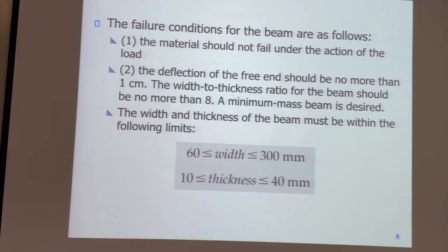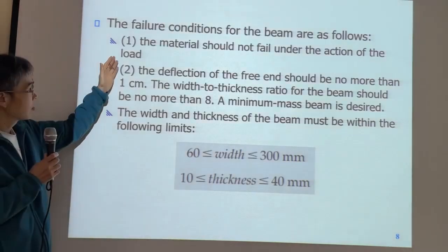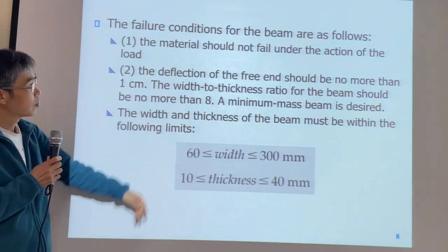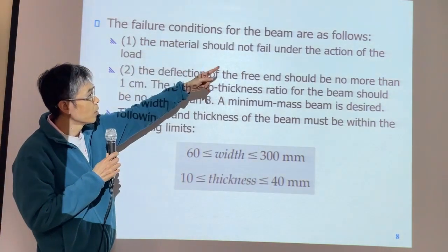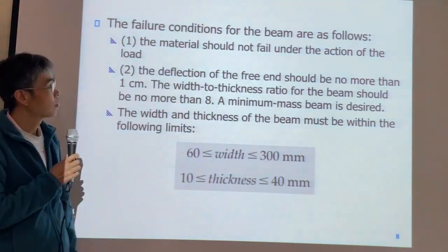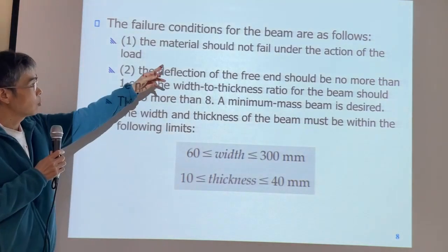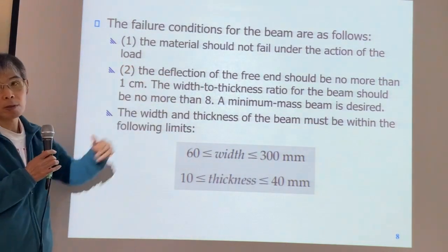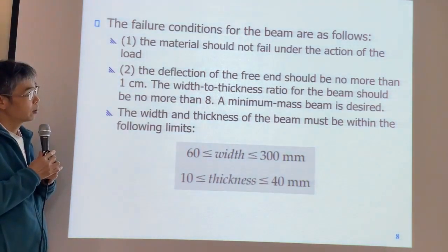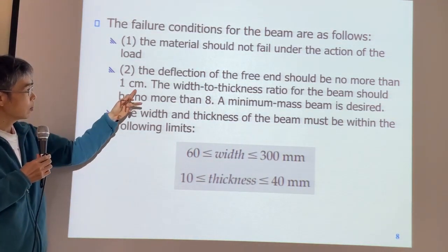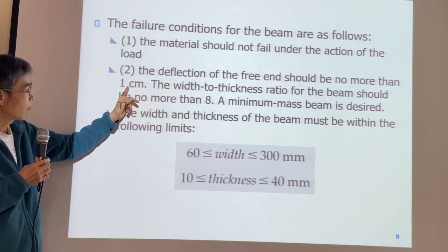Then after that, we need to collect information. So this is the information we need to collect. The fail criteria, the fail condition. So the material should not fail under the load. It cannot fail. So this is one consideration. And also we want to consider the deflection should not be more than 1 centimeter.